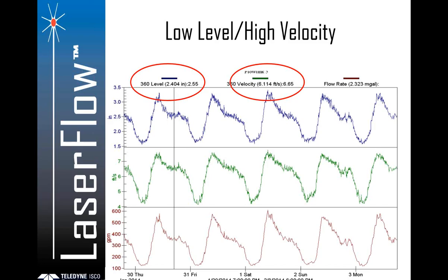And this is something, especially at a low water level. I mean, look at the bottom of the blue graph in the upper pane right there, we have water levels that are frequently below 2 inches. So again, with submerged probes, this can really cause some noisy or erratic data, and it's handled very nicely by the laser flow.